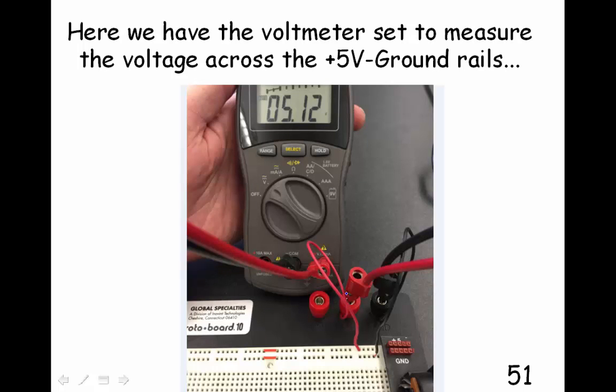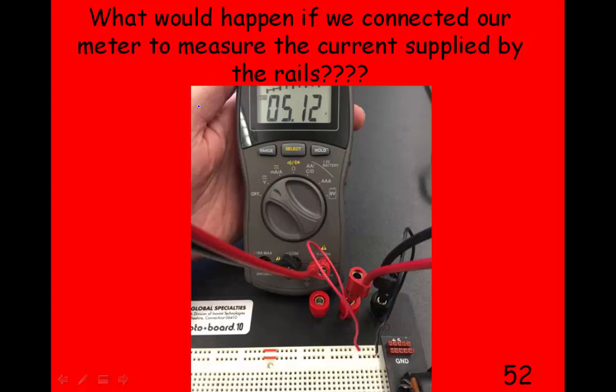Here's somebody who's got the multimeter switched to voltage, so it's measuring a voltage, and the multimeter is of course stuck into these two terminal posts. The red one is going here to our plus 5 supply. The black one's going here to the ground, and the person is reading 5 volts, just like they should.